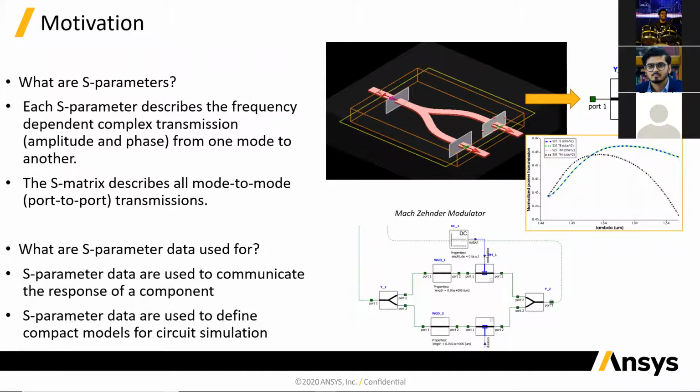And so when we looked at the ports in FDTD, in these types of simulations, what you would do is set up your geometry in FDTD. You can see the 3D geometry here for your Y branch, and these gray boxes are ports. So you set up 3 ports in your simulation on the 3 terminals here, and then you run the FDTD simulation. The mode source is built into the port, so you simply inject light into one of the ports,